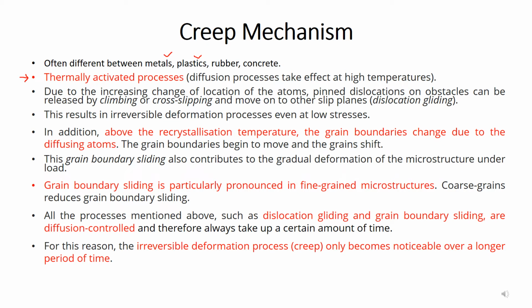Diffusion is the movement of the atoms inside the material from higher concentration to lower concentration. Due to the higher temperature, diffusion occurs. During diffusion the atoms move along the slip planes, and as atoms move, the dislocation movement occurs. So the hardening effects which were produced because of the dislocation pile-up, or because of the pinned dislocations, go away.